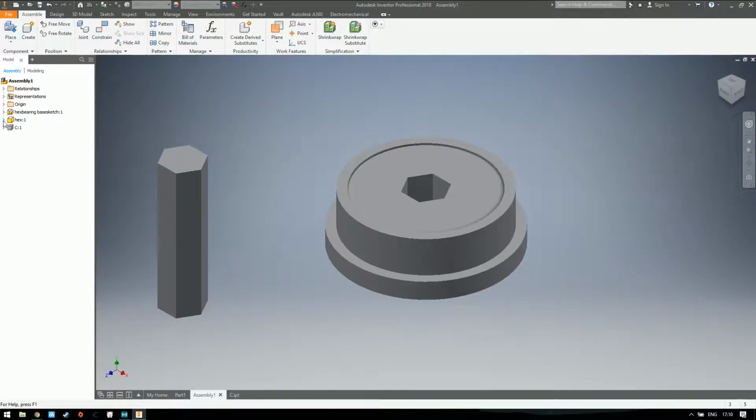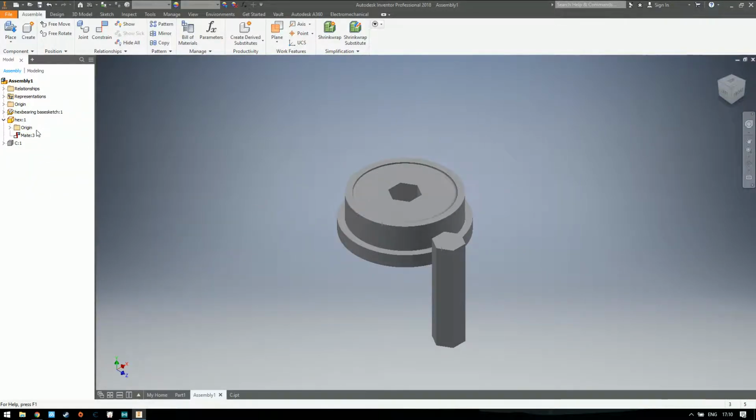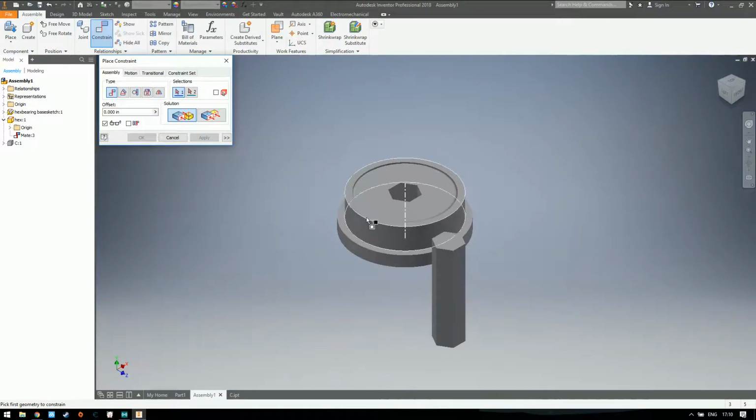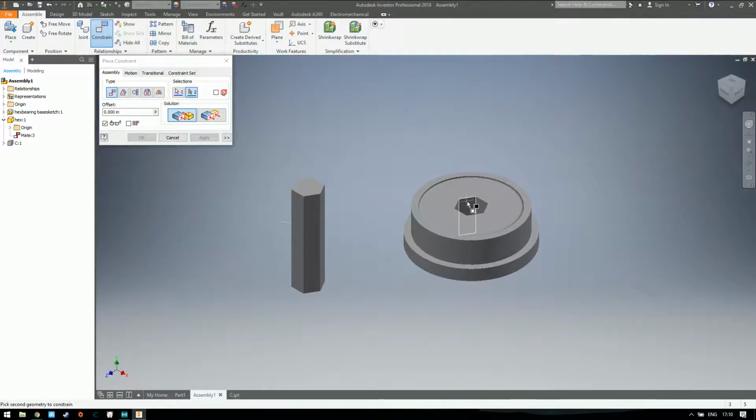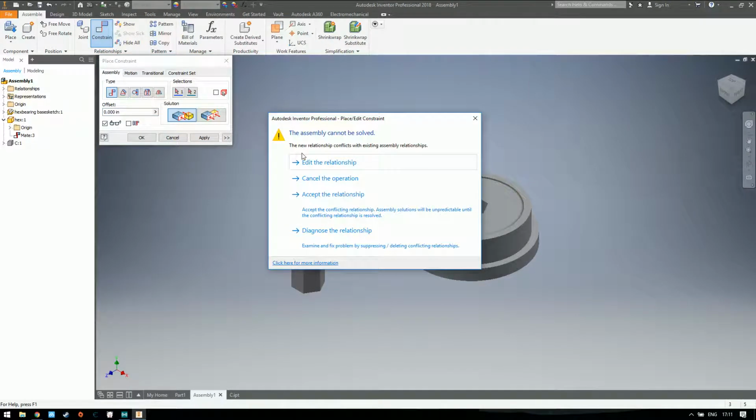Why? Because remember I told you guys before, the visibility is really one of our good friends. It's really going to be helpful. So you can always go to the constraint, left click on the arrow over here, right click on the mate, which is the constraint we did already, click visibility. This will help you show which face is connected to which. Lots of times I see people who didn't see which face they already connected, so they connect one of the other faces to the face that has already been made before. Then you click apply, and there will be an error.